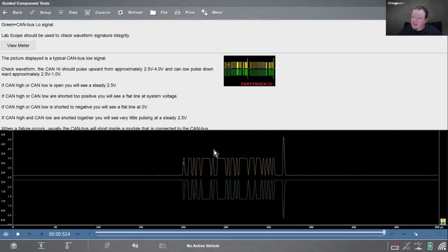If you see some spikes in the middle, that's a different story. And it'd probably be up in like the 5-volt range. So that might be something to worry about. And then you want to look at the tops, make sure they're not all skewed or messy.